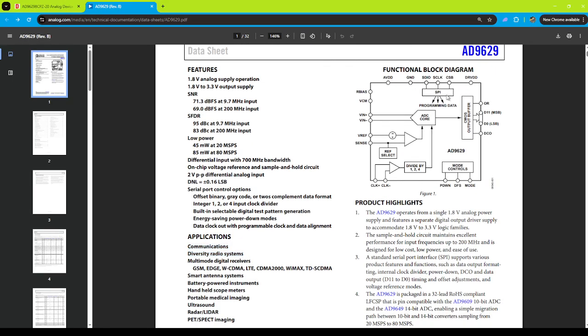So, okay, we see our SPI lines to get into the internal registers to set up the chip, actual digital bits coming out. These are all to pin strap the device to get into just basic configuration. Then we go into the SPI and actually program it. You actually feed your signal in here, reference, sense, and clock.